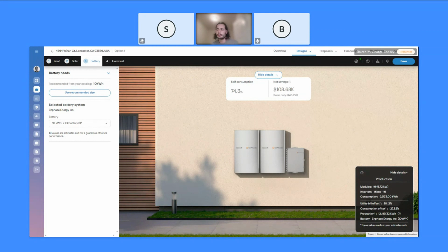If you're working on a flat roof, do you want to restrict the panels to be aligned to the edges of that roof, or are you going to allow 360 degrees of rotation? Some installers will install everything due south for highest production, but then you've got a funny angle between the rafters of the roof and your racking or your rails. So you've got a lot of choices here around how you want the tool to behave. Simple things like spacing or tilt values, ground mounts, which we didn't look at today, how you define what a low slope is. I won't run through all of those right now, but just know that you can customize it to the way that you like to design.